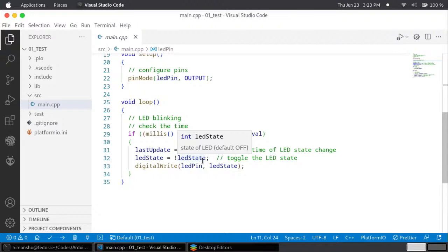Like, we have started Arduino, millis has the value 0, and now this value is going to be incremented with time in a linear fashion, and after 10 seconds, if I call millis again, it will say that it has a value of 10 seconds. So if after 60 minutes we call millis, it can say that we have a value of 60 minutes. This is how we track the time using millis.